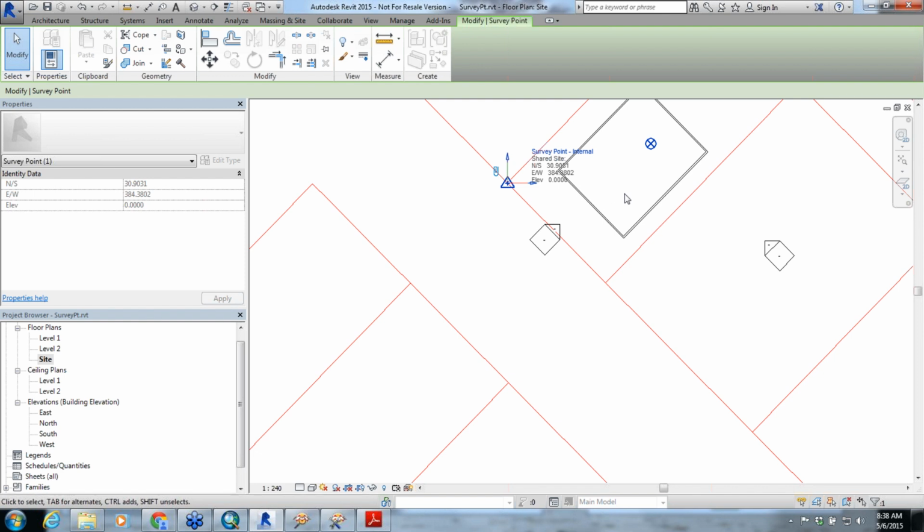The other thing to realize is that in this case, FME will export the survey coordinates. The coordinates of the model will be based on these survey coordinates. So it won't be centered around the base point. It will be centered around the survey point, given the offset. So you give them the survey point in the rotation of their survey point. So if we look at this in